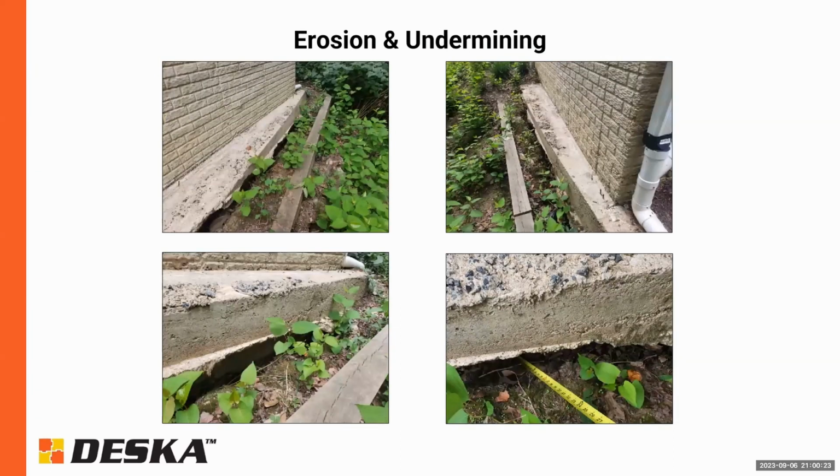So this is an example of significant erosion at the corner of a basement foundation. You can see there's what appears to be quite a void there, and you can see the footing. So, all footings are supposed to go down to a frost depth, which means the bottom of that footing needs to be below a particular depth in the ground. And in our particular area, it's 24 to 30 inches. In some areas in Minnesota, it might be 6 feet deep because it gets so cold. In other areas, maybe in Florida, there's no frost depth at all.